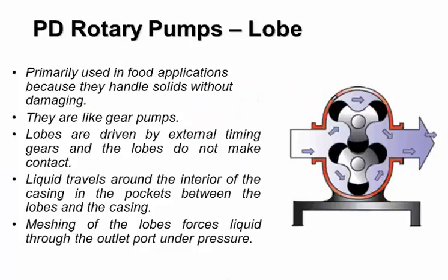And if you look at this rotary lobe pump, you'll see this more clearly. As this lobe rotor rotates in a clockwise direction, the liquid gets trapped in here, there it is there, and it gets pushed out from there. Now, what do you think rotary lobe pumps, what kind of liquids do you think rotary lobe pumps handle?